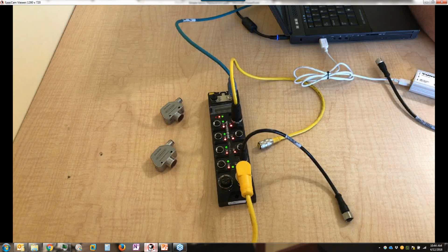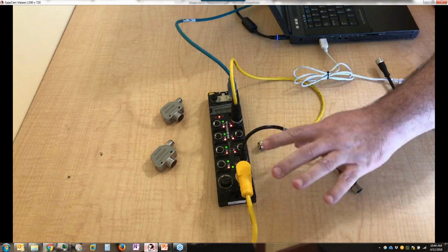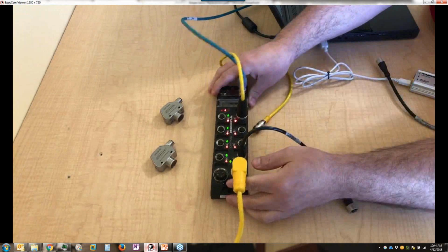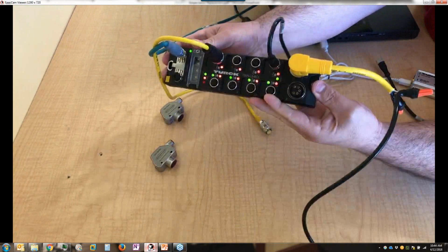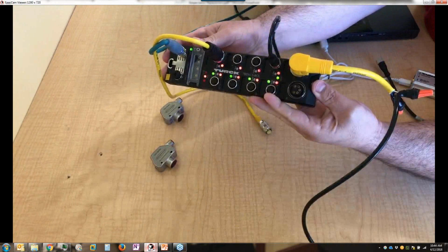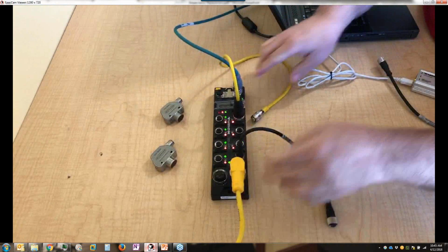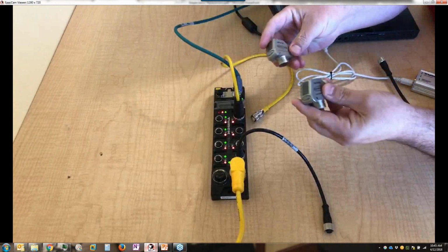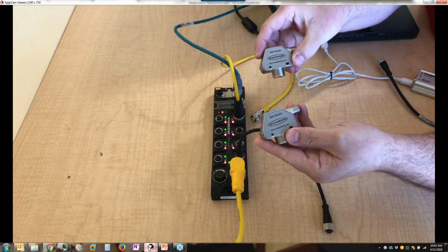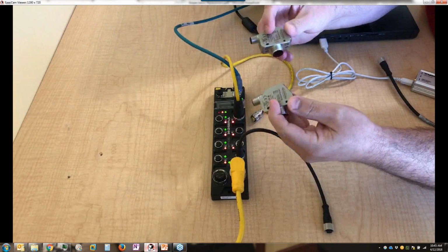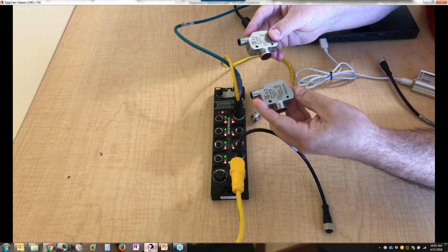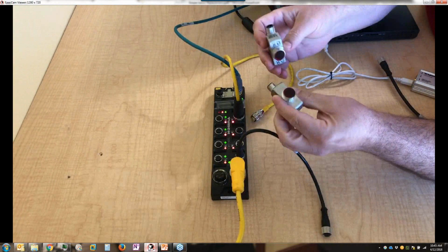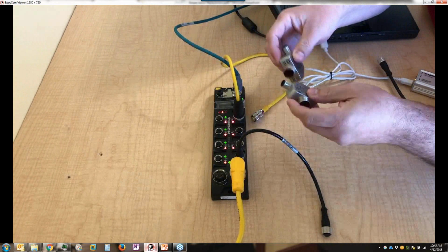All right. So it looks like my live video here is working, which is a good thing. So here's my TBEN-L5-8-IOL. I'm connected over Ethernet into the back of my laptop. And I've got two Banner Q4X sensors that are IO-Link. These are the 300 millimeter distance versions. And I've got one labeled BH for Brad Hart, and the other one is not labeled, so we can identify the differences.